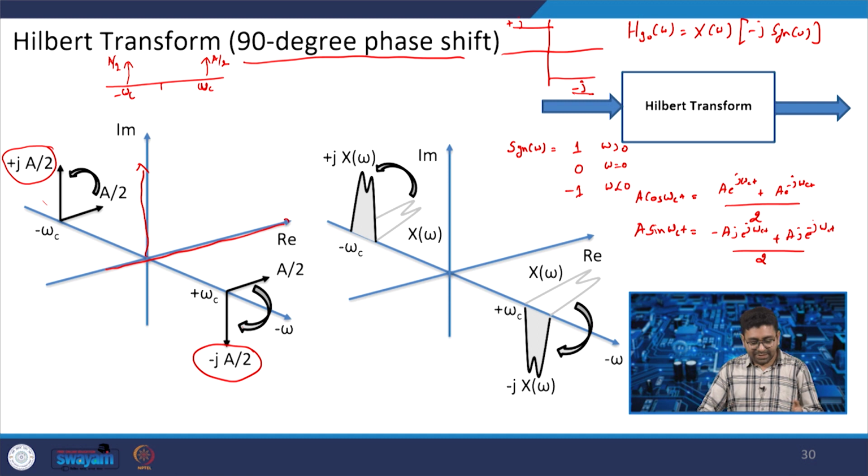It also has the advantage that you are moving from the real plane to the imaginary plane. Until and unless we move from the real plane to the imaginary plane, we cannot distinguish the difference between the image and the actual signal. Mathematically, we have an advantage by using the Hilbert transform: you can easily distinguish the positive, meaning desired, frequency and the image frequency.